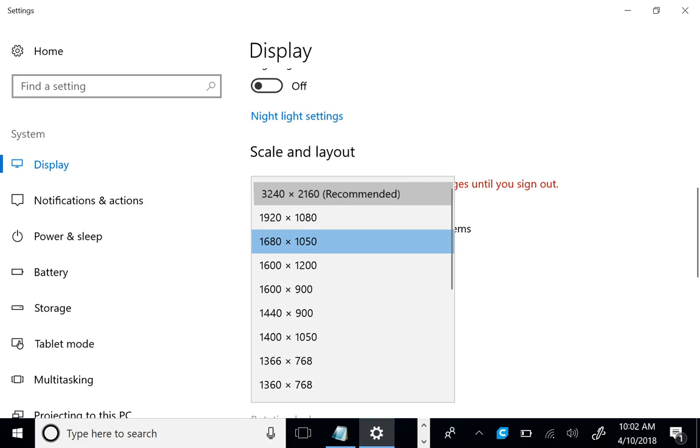Yeah, you can go over to infill, right? And right now the infill density is set to 22% for some reason. If I set it to 100%, it'll reslice. So now it remade instructions for the printer, right? And now it's basically filled in.